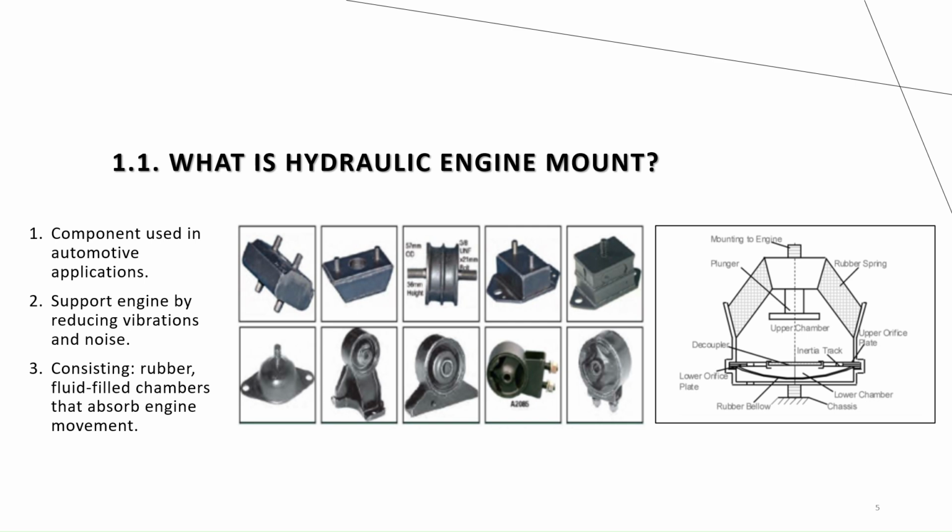It's on the bottom. The plates, which we also call flow channels, are two plates connected by the inertia track, and in the middle of that we have the decoupler. Hydraulic engine mounts now use ethylene glycol fluid, which is the same fluid we use in the hydraulic brake.